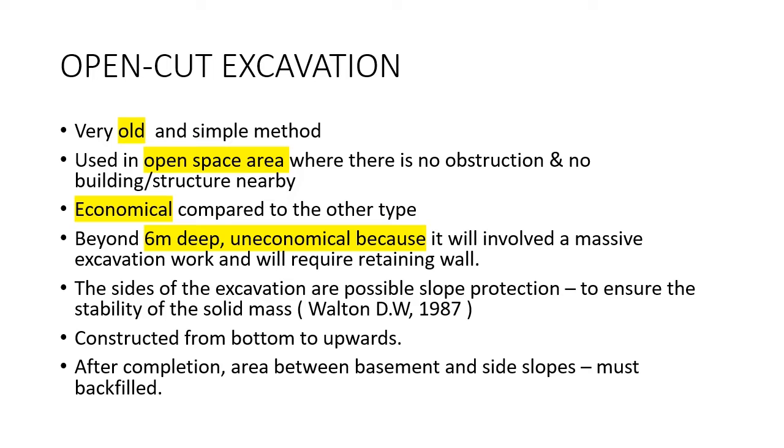The site of excavation needs possible slope protection. It is to ensure the stability of the mass so that it won't collapse. It is constructed from bottom to upwards, dari bawah ke atas. So this is the conventional method. And after completion, area between basement and side slope must be backfilled. So kita perlu backfill area yang kita slopekan tu, kita kena backfill balik.